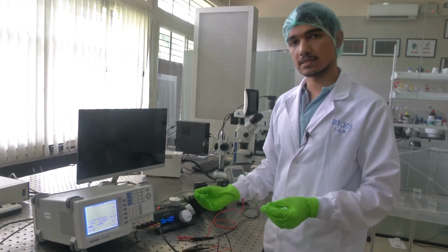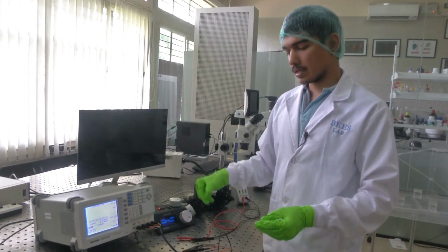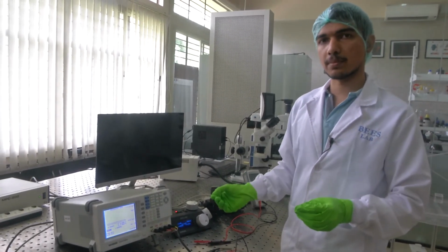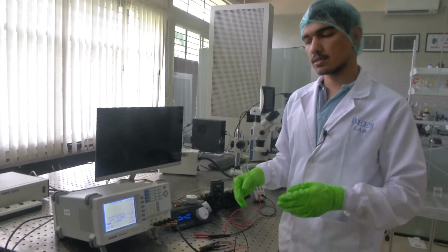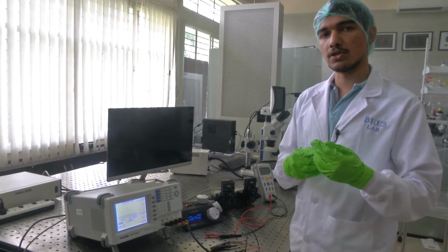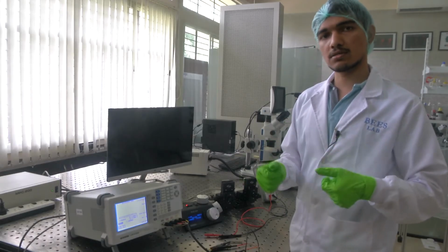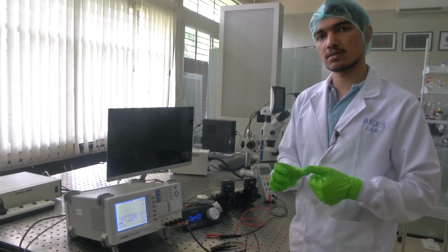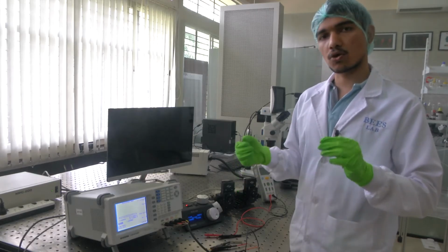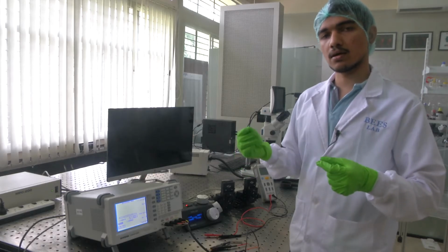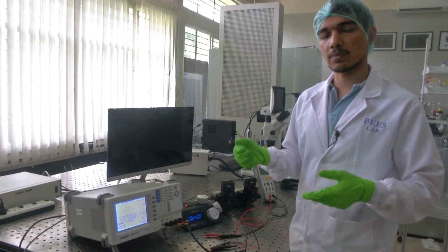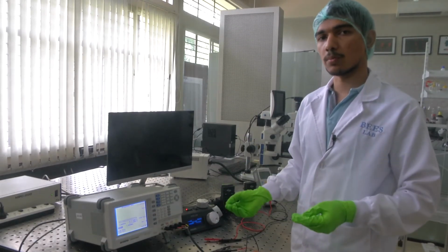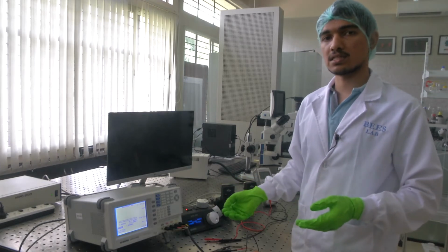The force probe passes a current through the DUT, which causes a potential difference to be developed. This potential difference will be dropped across the DUT as well as across the contact resistance. That contact resistance can cause a huge voltage drop in some cases, especially when we are measuring devices with very low impedance. So, the error will increase and the measurement will be invalid.